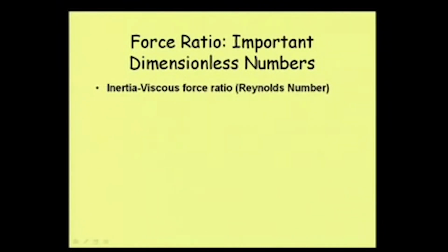First we will be talking about the inertia to viscous force ratio. Now what is the viscous force expression? Say Fv we can write as, at any point, suppose shear stress is tau, then viscous shear is tau, and if we multiply this by A, then we are getting viscous force. So what is tau? We can write mu into dv by dy, then we are having area.